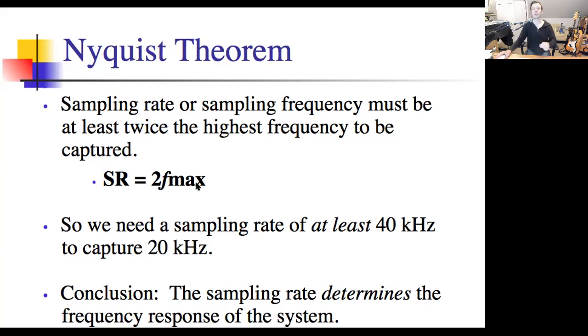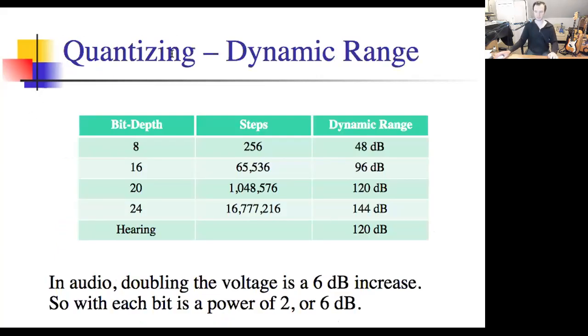So if you had an audio file and you're like, you know what, my grandpa can't hear anyway, so he can only hear up to maybe 8,000 hertz, your sample rate could be 16,000, and it wouldn't statistically make a difference. There are arguments about whether it actually does or does not make a difference, but arguably that's it. So that's your sample rate. Now, let's take a deeper dive into our dynamic range, which is determined by our bit depth.